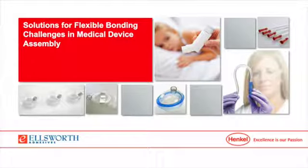bond line. So one method we often suggest to test if plasticizers are present is to prepare controlled and aged assemblies. You can expose the aged samples at 60 C for approximately 2 weeks and test the bond strength versus the control samples. So this type of conditioning will often drive plasticizers to the surface and result in a bond strength reduction. So if this is the case for you, we would suggest using a substrate with less plasticizer or one with no plasticizer at all. So I'll turn it back over to you, Molly.